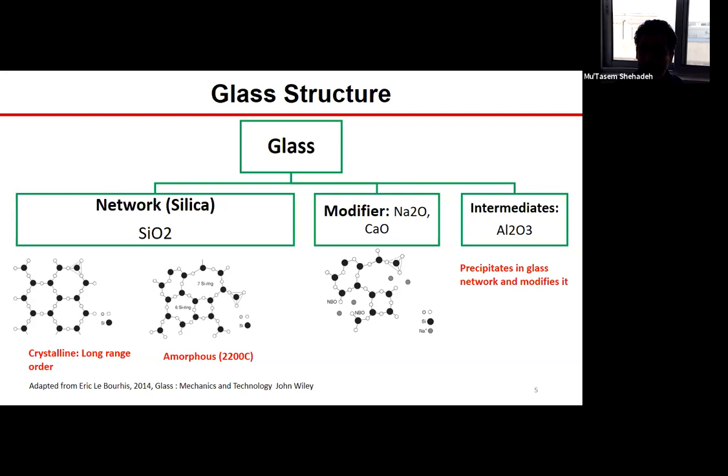That is to use simulation techniques at different length scales, starting from the electronic structure to the atomistic to the mesoscale, maybe using continuum or modified continuum theories, to finite element to simulate the behavior of structural components of the glass. So again, if you're interested in the physics of the behavior, the underlying physical phenomenon, then one can use ab initio coupled with maybe molecular dynamics. Or if you're after simulations of large-scale components, then we have to get some information from molecular dynamics that can be embedded in finite element to simulate and predict the mechanical response or the physical response of such materials.